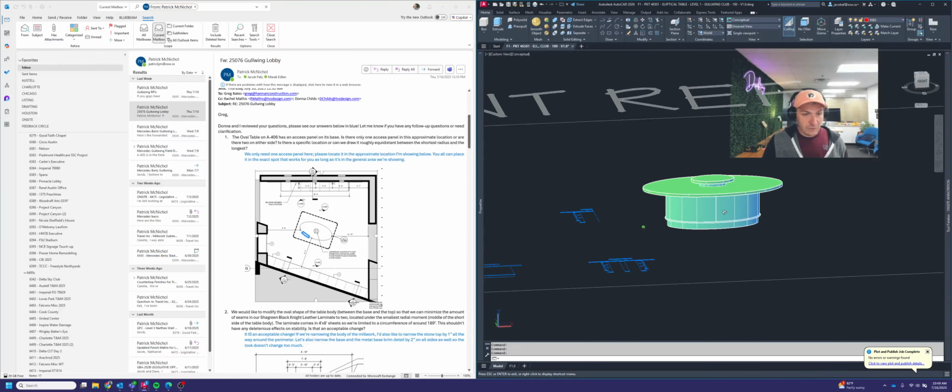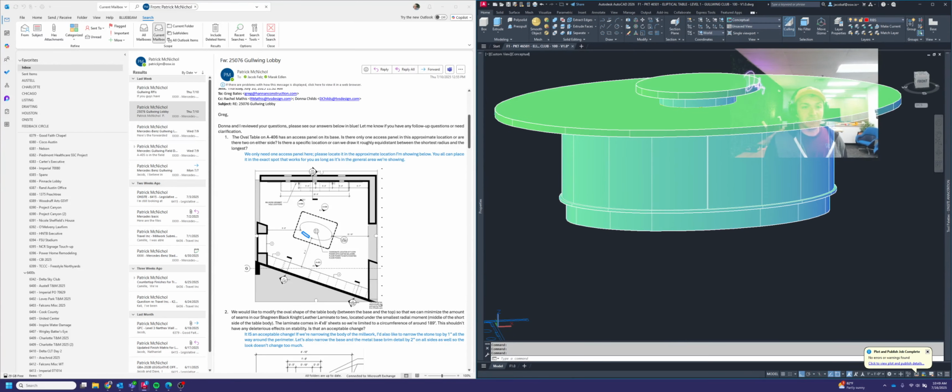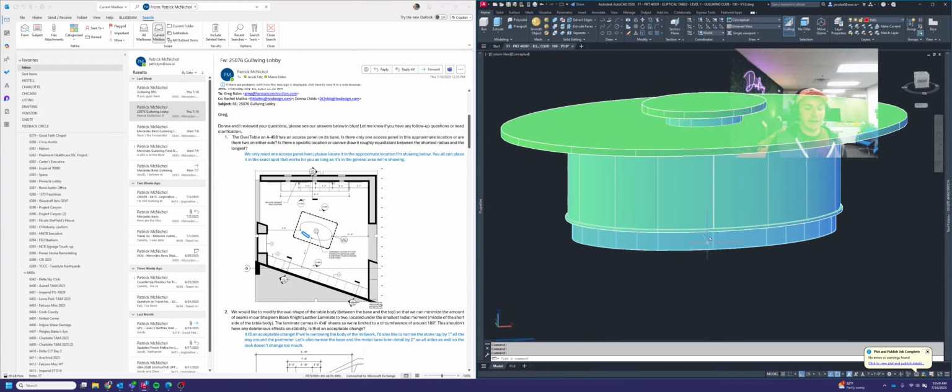Okay, so access panels. We may not have really gotten into those yet. I'm going to pull up a block that you can use as a reference to draw an access panel. This one will be slightly different. Generally, access panels in tables and desks are a square or rectangular panel that has a 1/8 inch gap that goes all the way around. And then the panel is typically mounted on, let's see, I'll pull up the detail here so you can see what that normally looks like.